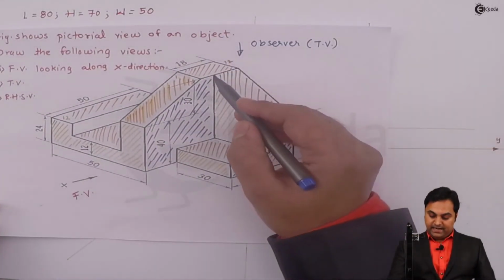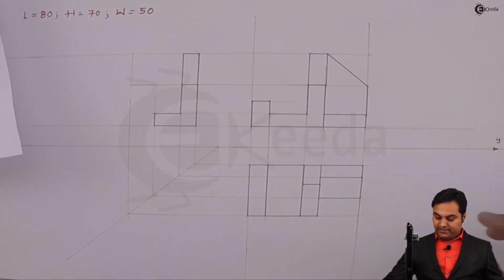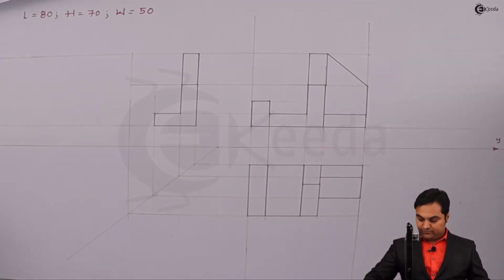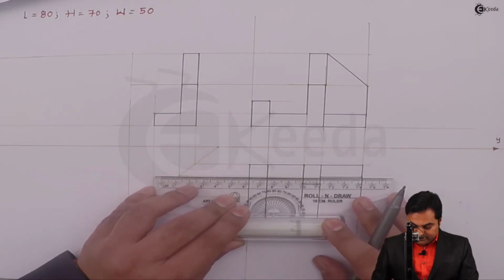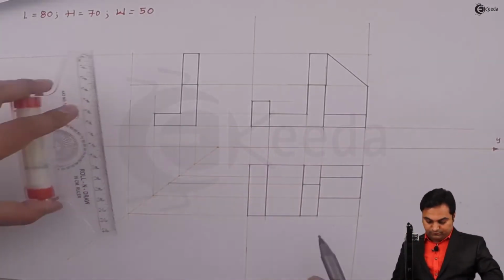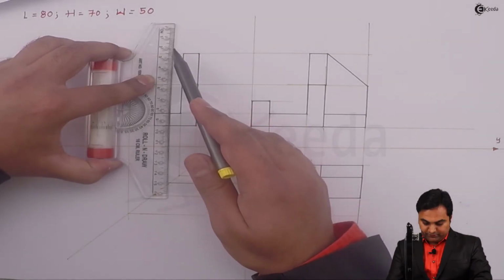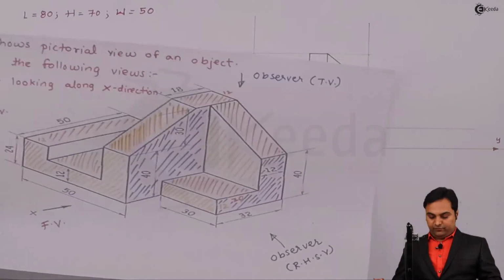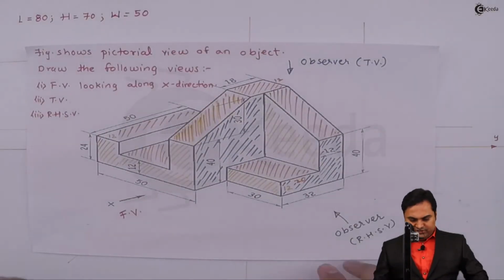For that, at first the width is 18 mm. That 18 mm width I can get it directly from the top view, because here is that surface which I am going to project, and getting it in the side view. So projecting the width. Next, it is connected 40 mm above. Now, after reaching at this stage,